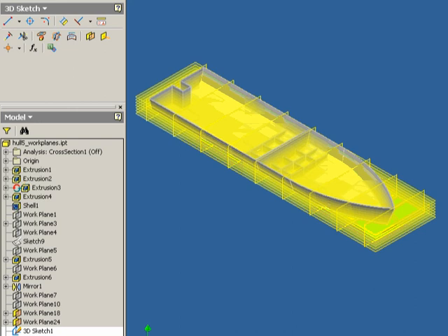Alright, in part one of calculating half breadths, I showed you how to create these vertical and horizontal planes that equate to station areas and also the waterline planes. So I'm going to show you in this video why they're becoming very useful in order to calculate very accurate measurements of half breadths, which is the distance between the center line of your boat and the hull of the boat. So I'm going to show you real quick. I'll just go ahead and get started.